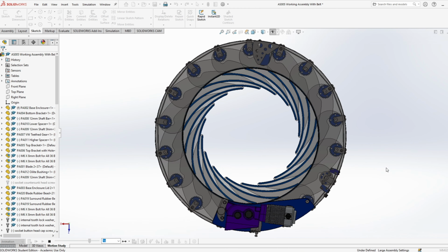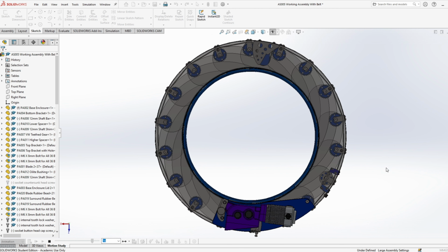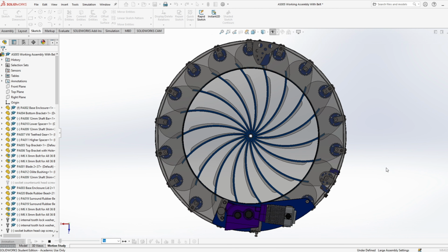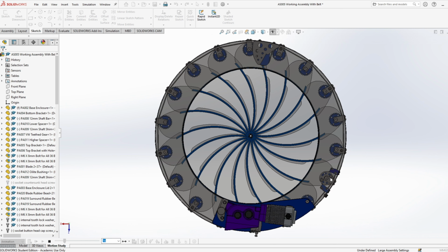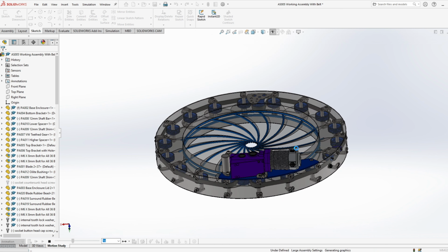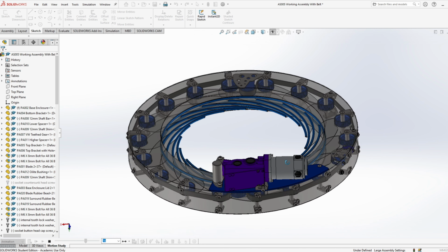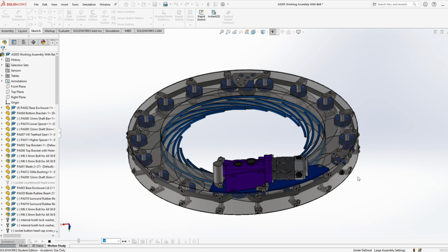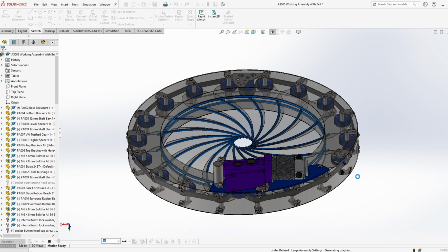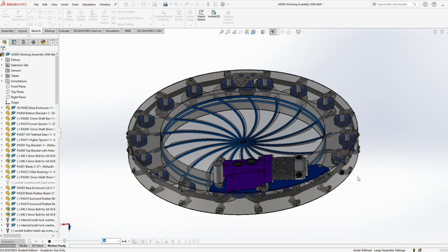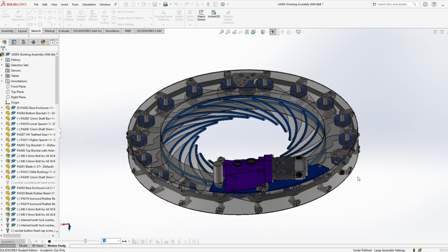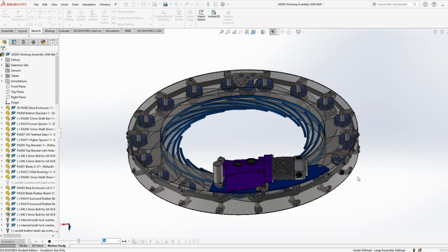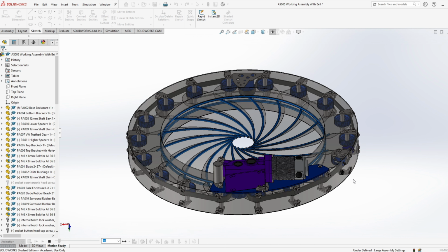For this last part, I'm just going to finish up by looking at the final 3 interesting facts. Okay, so each one of these 18 shafts was never perpendicular to the base enclosure in prototype 2. There was always a 1° angle across all the shaft assemblies in the same direction to allow the blades of the diaphragm to mate better through the opening and closing cycles.